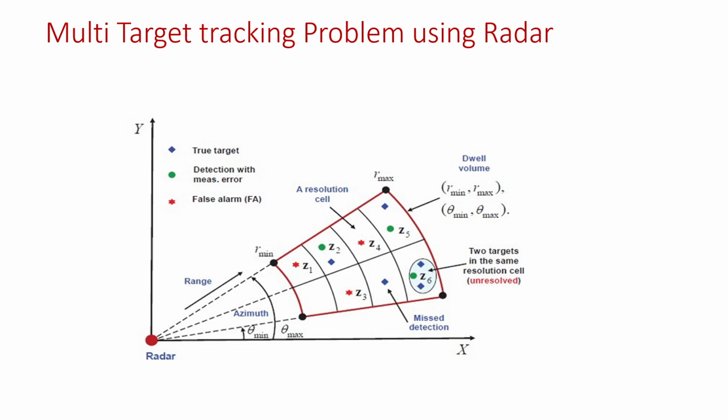Suppose I am giving a standard example. Suppose two parallel vehicles are there and the spacing of the vehicles is within centimeter range, say 1 centimeter, 2 centimeter. Okay. And you are tracking with an automotive radar. Your radar will give only one measurement. It is very much possible, because if your sensor cannot resolve, you cannot do anything, and then all these tracking algorithms cannot do anything, but this is a problem. So, these are called group targets. For a certain group of targets, if your sensor cannot identify that they are two, it will give you only one measurement. This is a very important thing, called the sensor resolution problem.